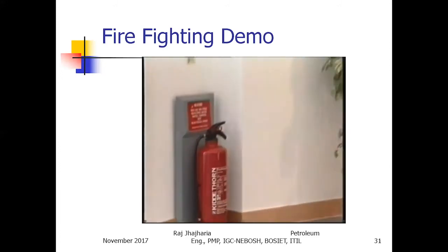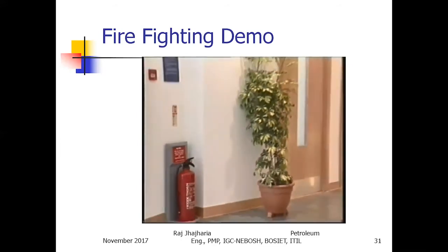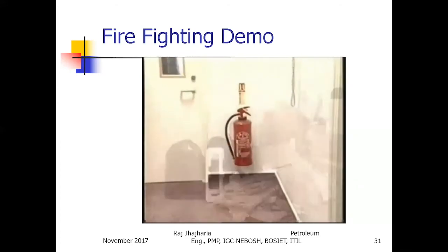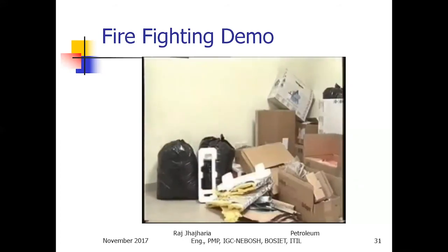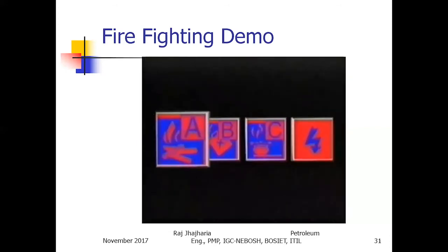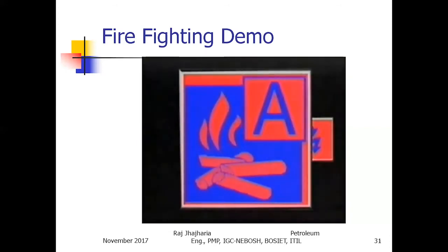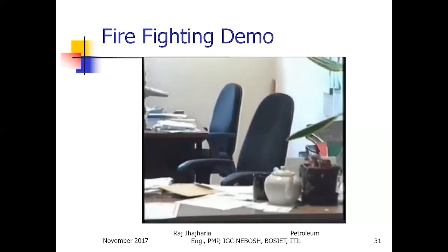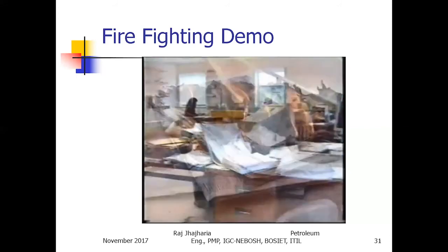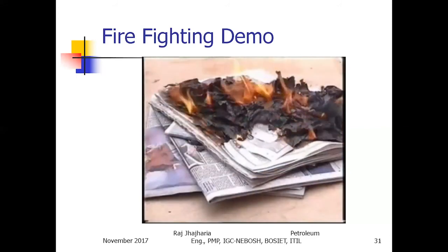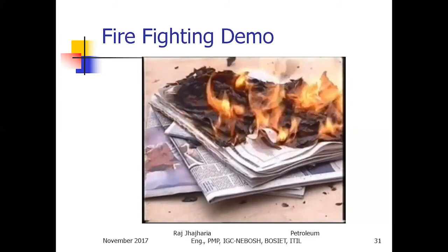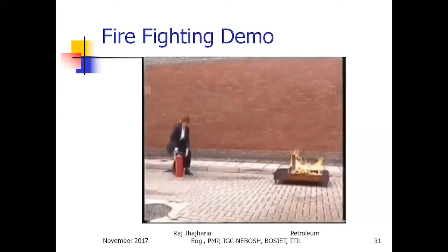The first type of extinguisher we'll look at is water. Water is the most common extinguisher in the majority of buildings, as the main risk from fire is usually presented by normal combustible materials. Materials which fall into this category include things like chairs, desks, papers, furnishings, and so on. The most effective way of extinguishing this type of fire is to remove the heat, and using water is the best way of doing this.